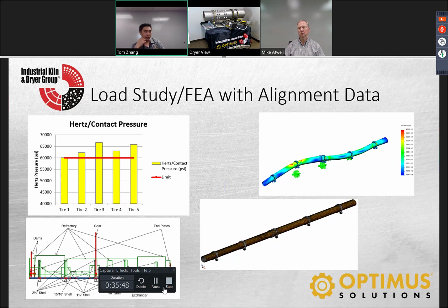And there were circumferential cracks. So again, this just further shows that you want to make sure it's aligned. You want to make sure that the details of the alignment are there so you don't get circumferential cracks. If you do, circumferential cracks are hard to deal with. When it's hot and it's rotating, if you don't catch it within 30 minutes or so, or stop the kiln immediately, you will have more than one kiln.